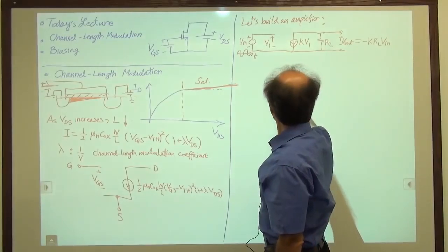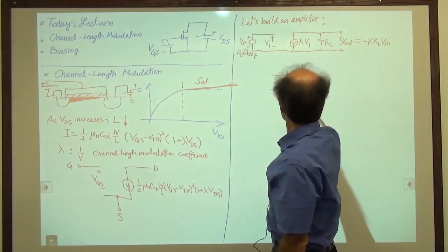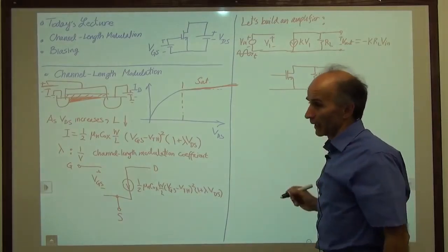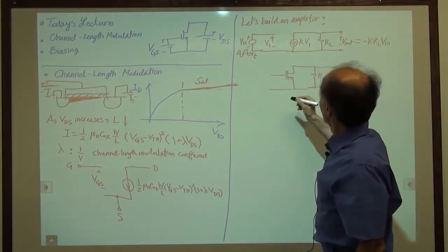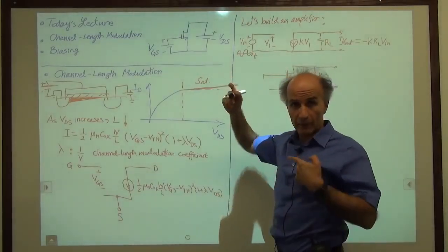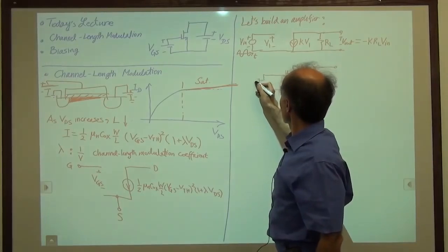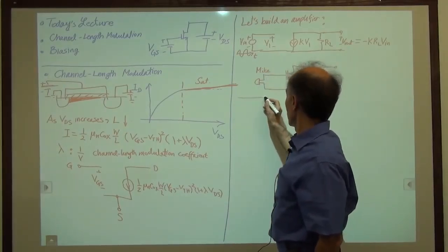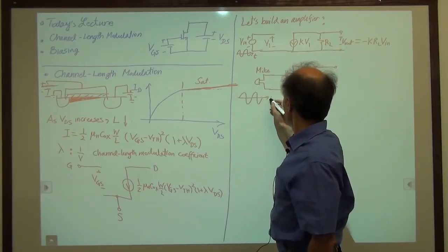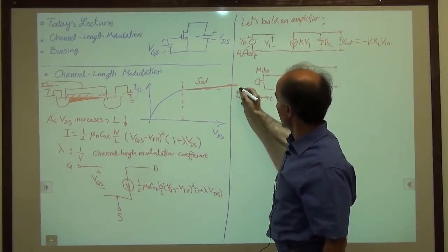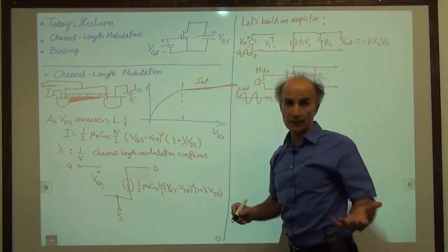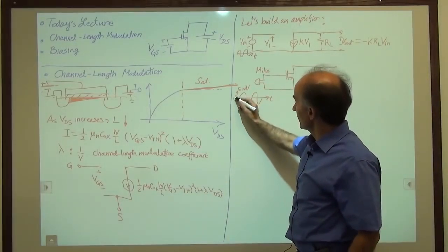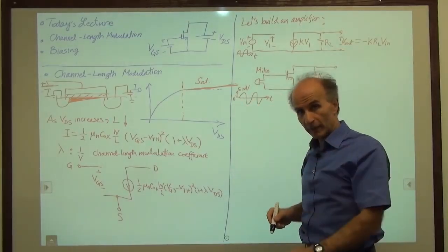All right, here it is. We have our voltage-dependent current source like this. I'll just copy everything down here. So I have RL. And then I have an input, for example, from a microphone, right? So I will draw a microphone symbol here, mic. And again, this microphone signal looks like this. It has a signal that goes up and down like this. And it has some amplitude, some peak amplitude, let's say 5 millivolts. Just as an example. Okay. Now the microphone signal starts from 0, goes up by 5 millivolts, and goes down by 5 millivolts, around 0.